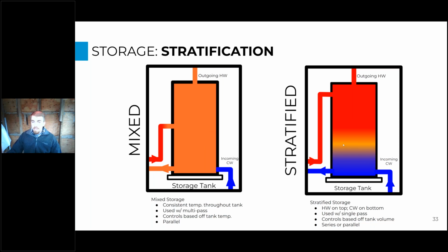But with a stratified storage tank, we don't have that overall consistent tank temperature. So if my temperature sensor is right here in this tank, even though a third of my tank is filled with 50 degree cold water, my temperature sensor still might be reading 140 degrees. So my temperature sensor here is not indicative of how full the tank is just based off the temperature alone.